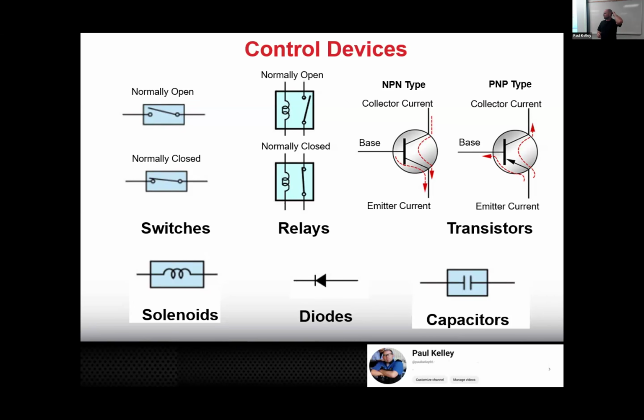The service manual will specify, based on the size of that capacitor, how long you have to wait before you start probing around and you accidentally trigger an airbag deployment. Makes sense? So capacitors are used in that function.